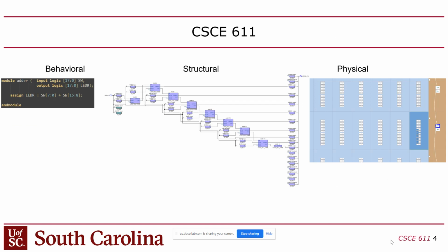The only difference is instead of the blocks in this block diagram being logic gates, they're actually just blocks that represent physical components that are available on the FPGA. And then when you're ready to deploy it in the field, you go through a process called place and route, where you take each one of these blocks and you decide, much like you did with the breadboards, where you want to put each one of these blocks on a physical substrate of some kind. In this case, it's an FPGA, so there's these empty slots where you can allocate each one of these.